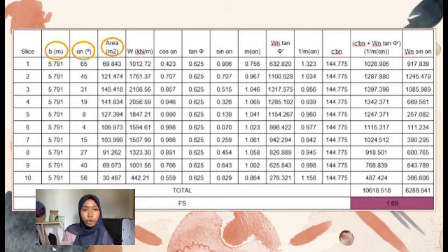From the slope drawing before, we can obtain several items that can be used to calculate in the table, such as number 1, the angle, which is the angle from the midpoint of slices and the line of the circle. And then number 2 that we can obtain is the area of the slices, and the third one we can obtain is the width of the slices. So this is the example of calculation by using the radius of 30 degree and ratio 1:1. So we obtain 1.69, which is already near to the 1.7 that we have assigned before.